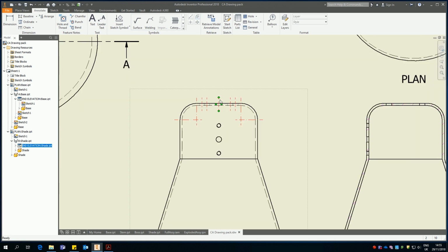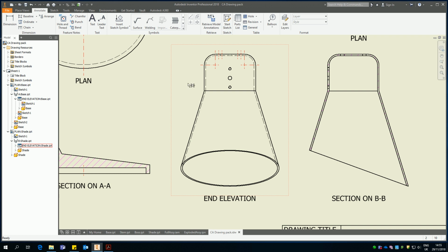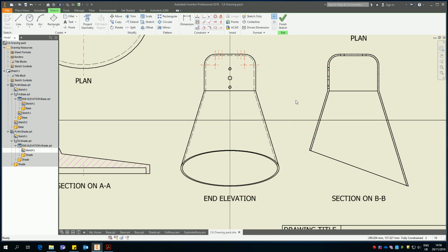And in fact, I'm going to delete that one off. Oh, I don't want to delete the full view, just that one, because I'm going to have one single center line going down the middle. So again, back to sketch, apply the sketch to this. The reason for this is if I move this view, it moves with the sketch. So it's important that you are applying the sketch to the particular view in question.